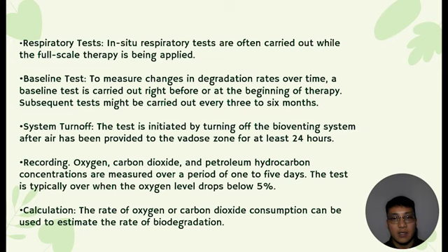In situ respiration tests are often carried out while the full-scale treatment is being applied. Next is baseline test. To measure changes in degradation rates over time, a baseline test is carried out before or at the beginning of treatment. Subsequent tests might be carried out every 3 to 6 months.